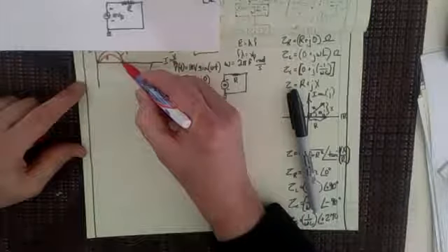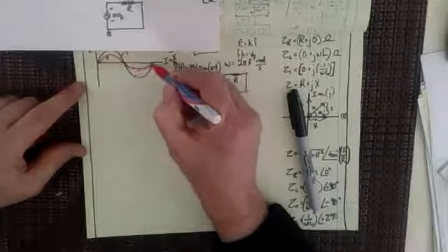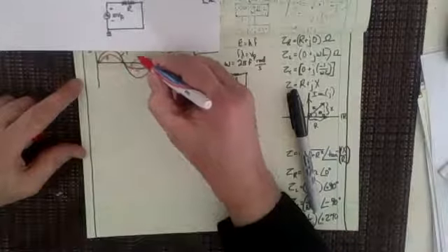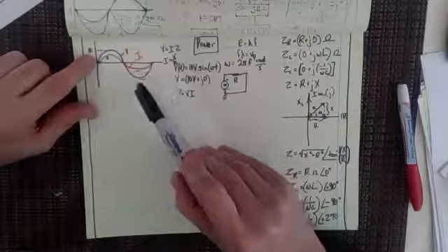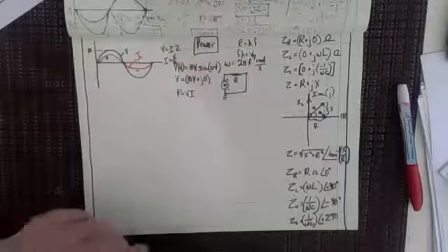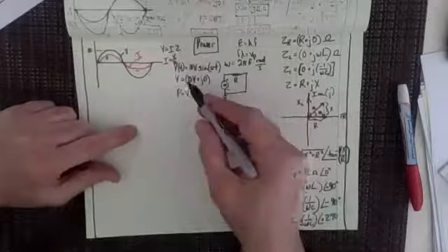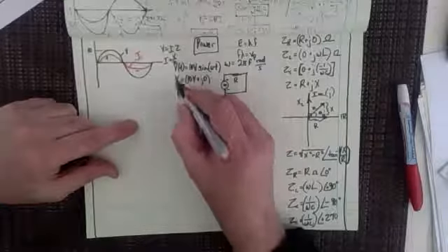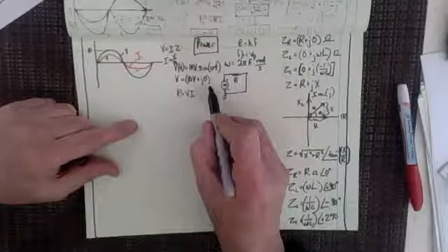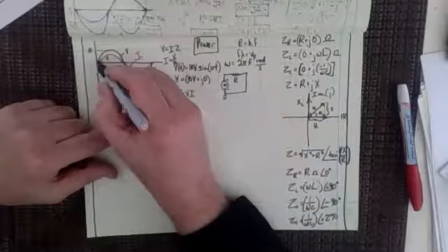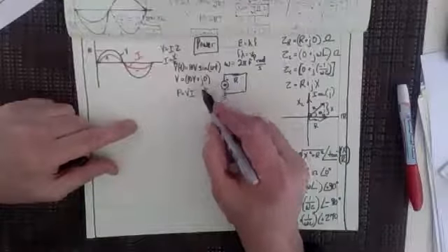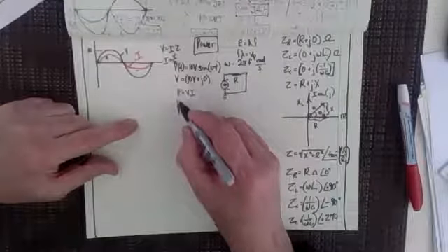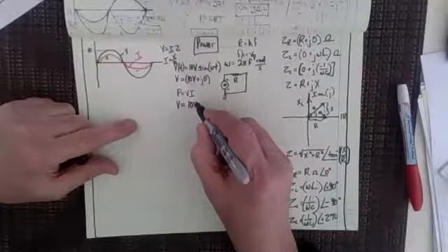The current is going to be in phase with the, and there you go. I've got a pen that's a red pen too. Look at that. So you can see that the voltage and the current are in phase with one another. And how do I know that? Well, let's actually look at this. Now we know that this is the time domain waveform. And then we know that this would be the representation of the voltage because the voltage is starting right at 0. It's our reference. And we could also write that voltage as V equals 10 volts because that's the magnitude.